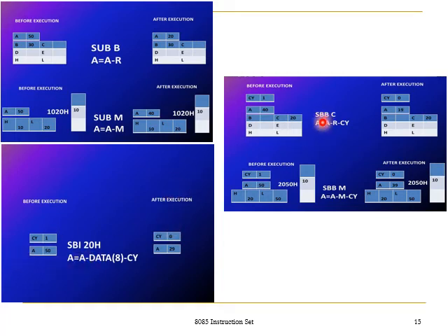Next we see the example of subtract with borrow, the register specified. Similar to add with carry, it is going to subtract the content of the specified register from the accumulator along with the carry. So you assume that the accumulator is holding 40, the B register is holding 20, and the carry flag is set to 1 before execution.